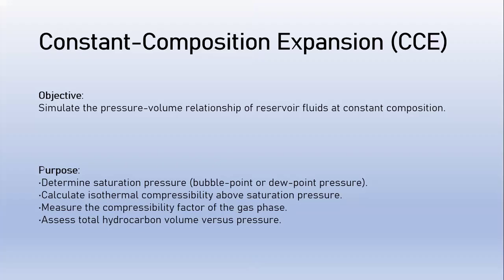So then we move to the constant composition expansion tests. The reason why this test is being carried out is to simulate the pressure volume relationship of reservoir fluid at constant composition. The purpose of this experiment is to determine the bubble point or the dew point, which is also called saturation pressure.